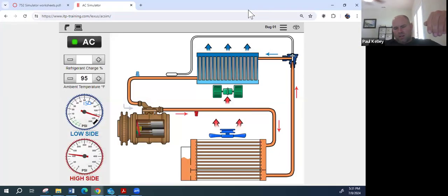So if a customer comes in and their AC doesn't work at all, and you find that their system is slightly undercharged, that goes more with the AC blows cool but not cold. Slightly undercharged doesn't make the compressor not work, right? So that's why I really like these simulators. So I agree we found something. Now, if it has over 100 psi, that's enough to get the compressor to kick. That compressor should run. Why else would the compressor maybe not run?